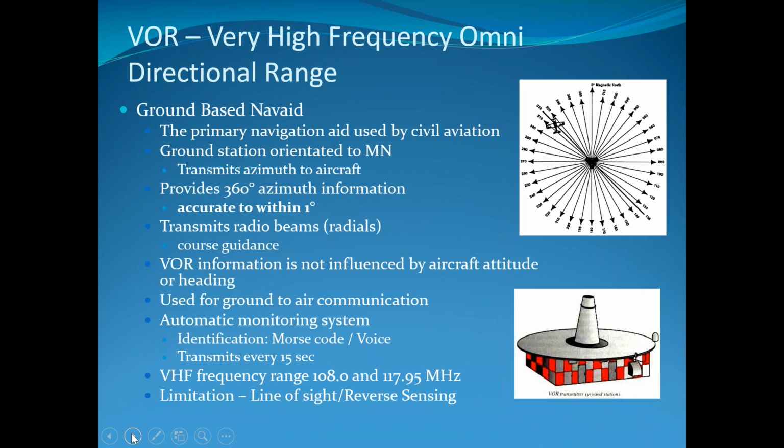There's always going to be a little bit of a variance on what your receiver in your airplane, or your heading indicator, thinks is magnetic north. So if you were to point it north and just keep flying north thinking that you're going to reach the North Pole, because of how the magnetic variance shifts as you get closer to the poles, or further side to side, it'll start to pull you into a different direction. Once you get really close to the poles, those things are pretty inaccurate, because it's going to take you in circles essentially, once you get close enough.